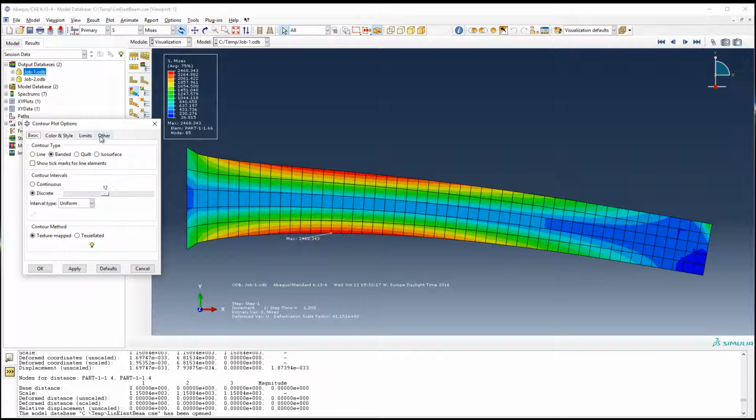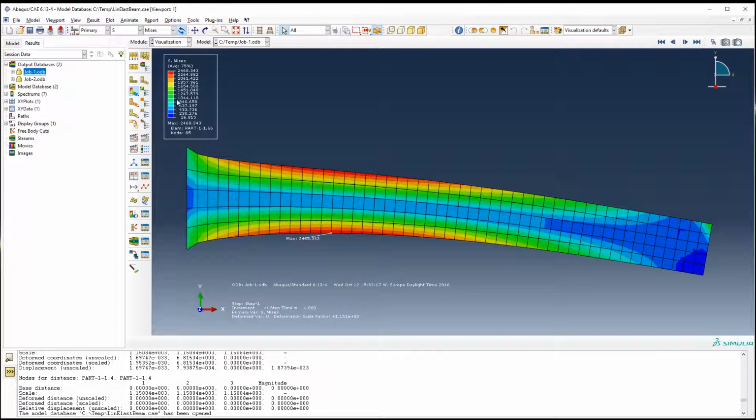Okay, if you go back to basic, and let's actually not go into this yet here. I'll save this for later. Let's talk about the actual number representation here. These are floating point numbers, and this is really fine for now if you have low numbers like this. But I have low numbers like this because of one reason. This thing here is huge. So you can actually check out the length of this, but I can tell you that the size of this is 100 times 10. And then you are asking yourself, okay, what's the unit? 100 doesn't tell me anything. Well, the unit here is like everything in Abaqus. You set the unit yourself, so you're responsible for handling your units. And right now I've set this to meters, I believe. So I've calculated everything in meters, SI units. So this is 100 meters times 10 meters.